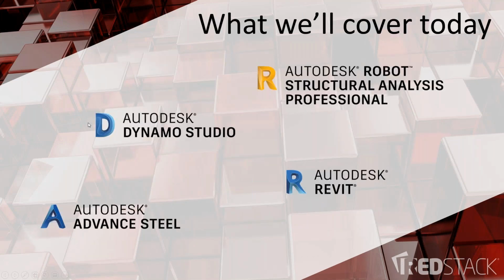I'll just go back to our overall. We did a little bit of early stage scripting and programming in Dynamo Studio. We did some of the design inside Revit, so we can place other members and structural connections in there. We can do the analysis inside Robot Structural Analysis. We can send those changes back, and we can also work with Revit and Advanced Steel to get our fabrication drawings. So someone in a workshop somewhere can cut steel and cut holes in it, and then send it all out to site and put it all together like a big Lego piece. So that covers